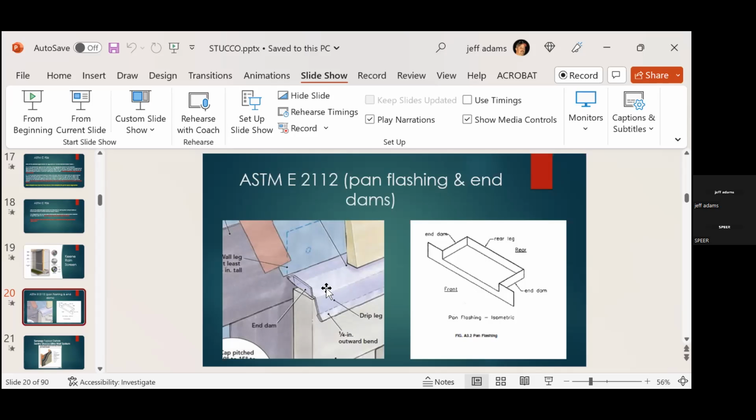I've noticed that most of the window manufacturers all sell their flashings. You can order them when you order the windows, and every one of those flashings per the ASTM, 100% of them are cut too short, and they're only protecting the window frame itself. The flashings do not extend out past the nailing fins. So that 1 inch, 1.5 inch wide nailing fin is open on each side to allow water to get behind it. So their flashings are really a major conducive area for water penetration and issues.